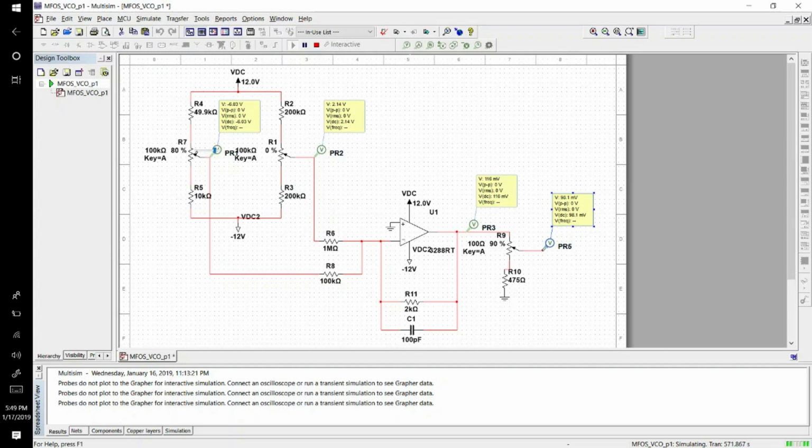So we can see that by varying the potentiometer states, it can go from negative 9.6 to 3.4, so it's significantly smaller than our calculated range. Why? Because there is current. First of all, they are in parallel, and also there is current that is going into the feedback of this op amp.